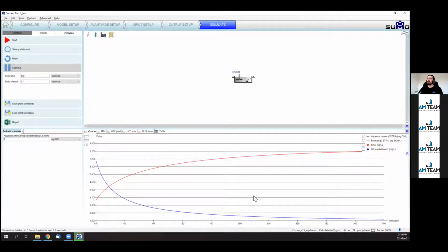Why is this happening? For a complex net of reasons, which is linked to the complex net of reactions that lead to bromate formation. In a nutshell, you leave more chances to the reactions that take away the Br formed in the middle of the way of going to bromate, to the final bromate formation, to be dragged back.